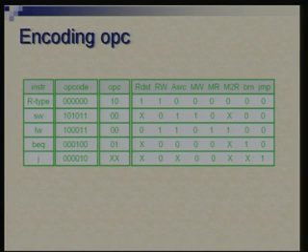So now the truth table is actually complete. This main controller has 6 bits as input, the 6 opcode bits, and you have 2 bits of OPC plus 8 bits in the other table. Altogether these 10 outputs have to be produced. So it's a 6 input 10 output circuit which we now need to design.